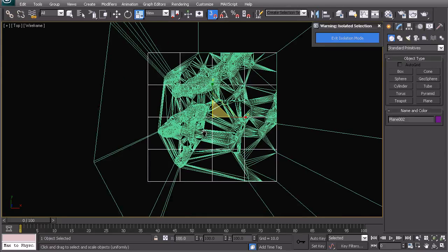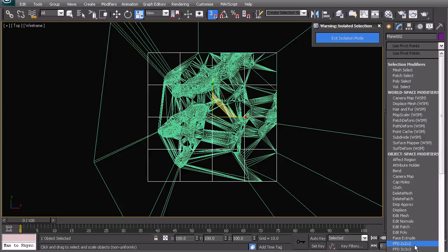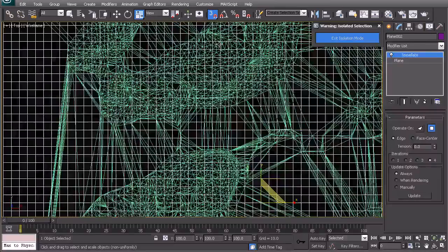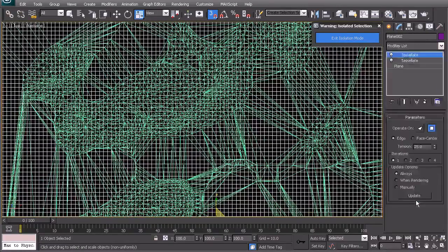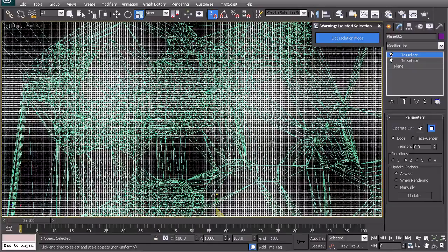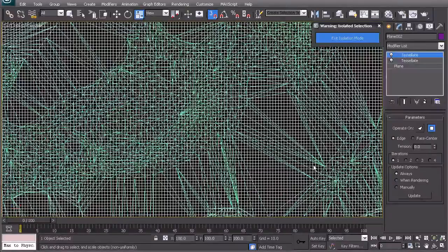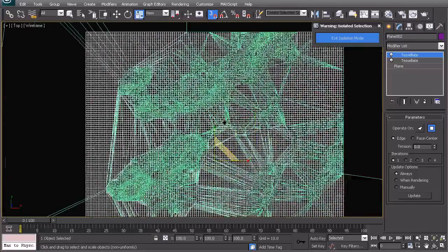Next, what we want to do is tessellate this square so that we have a finer mesh which is going to conform then onto our original terrain. You can do that by going into tessellate, adding a modifier. You can just undo the tension by right-clicking, go into 4, and I think looking at this we can add a little bit more detail just so that we have a neater looking mesh in the end. So we go to tessellate again, we do the same thing. We can go into 2 and we can see if that's too much. I think that's a little bit high, although if I had the computer power I would go for this level of detail, but I'm going to keep it quite simple just for flexibility's sake so that we can easily zoom in and out of our project.